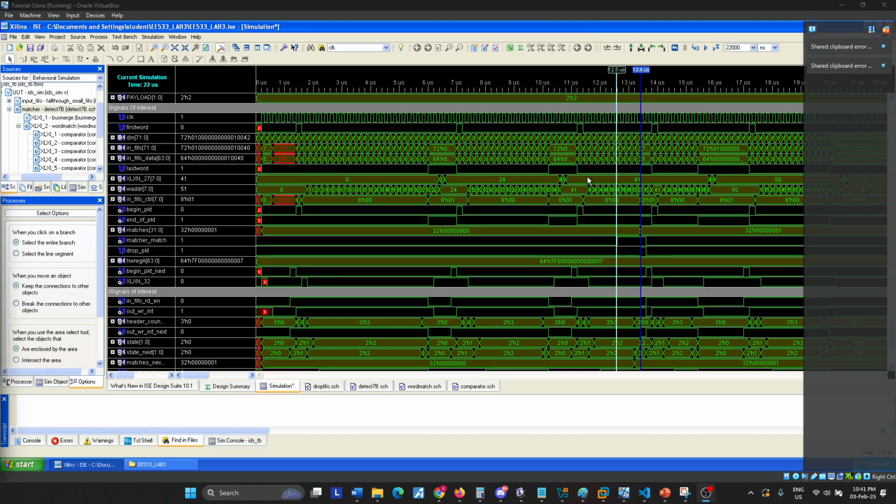Because the count actually matched 10 of the test bench, these 10 packets will be dropped. If somehow our pattern was matched somewhere here, then more packets would have been dropped. Essentially, the packets would only be dropped between the first and the last packet. All of them would be dropped, and the history pointer would then update my dual port memory's pointer. So this is how my pattern matching works.